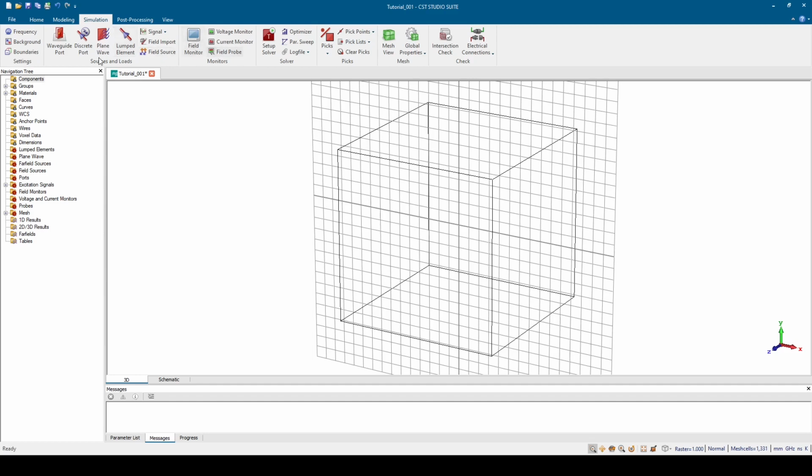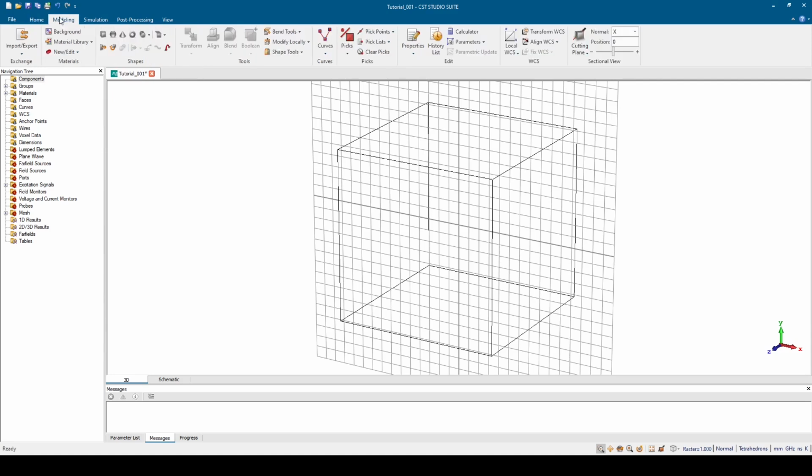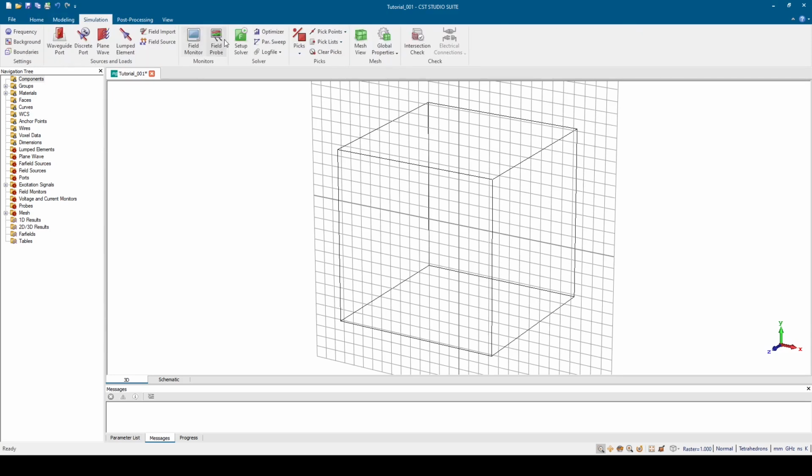Okay, and then from this tab basically we can decide the type of solver. So not from here, but we can go from home, deciding the solver, frequency domain, and here we can actually go if we have any excitation source or something, but yet we did not create any ports, and that's why we are not allowed to play with it. Okay, so now we are ready, the grid is adjusted to our scale, our dimensions. So let's do it then.